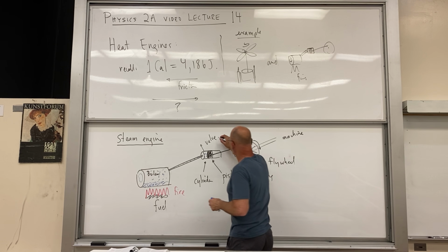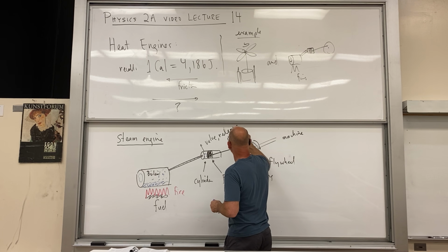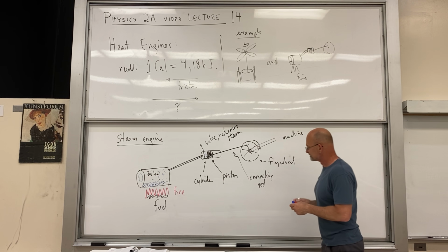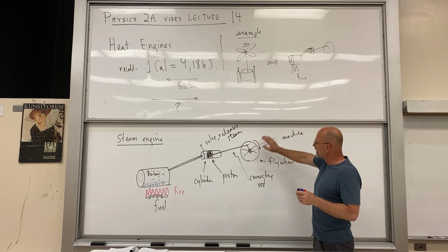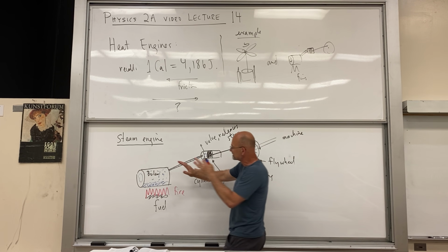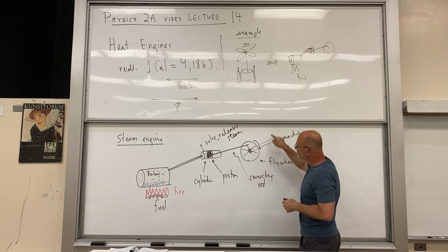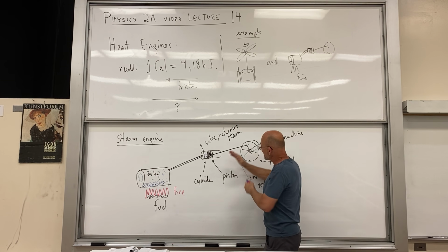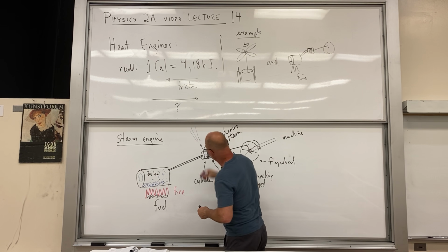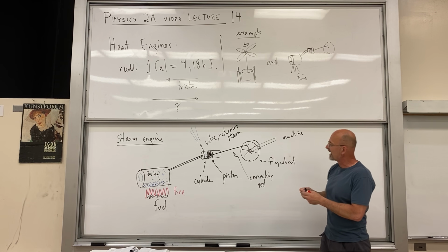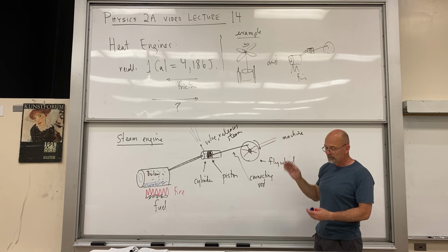So the valve releases steam. Okay. Good, so you can make clear how this process is working. The constant supply of steam under pressure pushes the piston forward, the wheel rotates. On the way back, the valve opens, and here I'll draw some steam being released. So every half cycle, steam's being released, the other half cycle, work is being done.